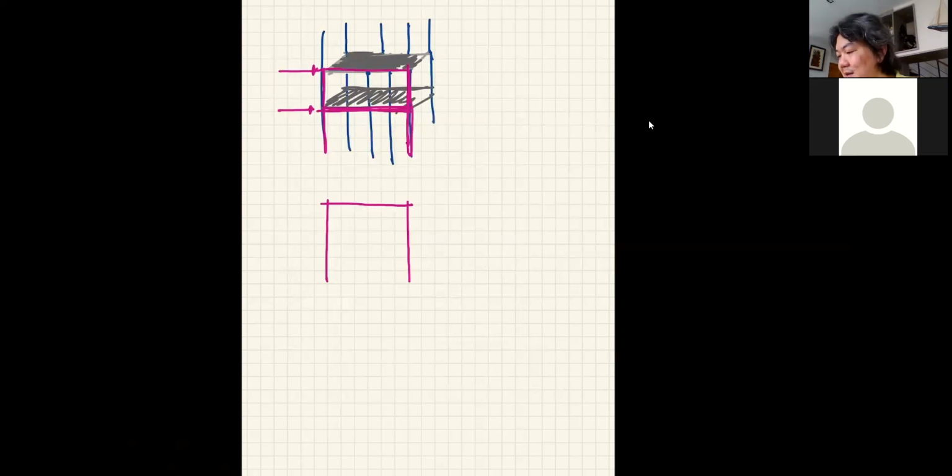Okay, and generally building has many floors, so it means that your frame can be very, very complicated. Like this, with so many floors. And generally, if I want to make it a determinate structure, I can give you a simple support system like this. So you have 3 reactions, correct? But in the real world, you don't have a simple frame like that.